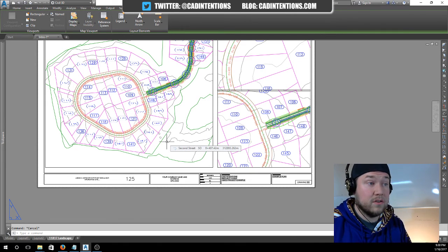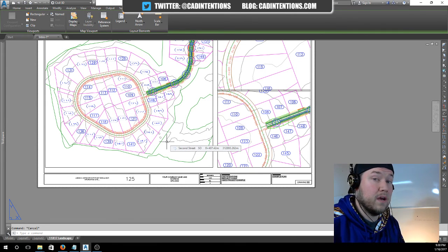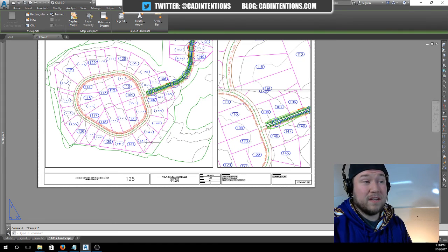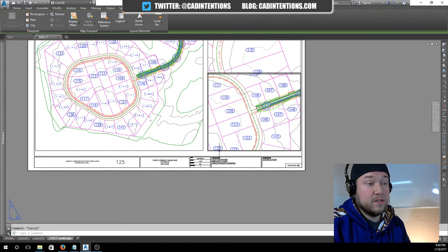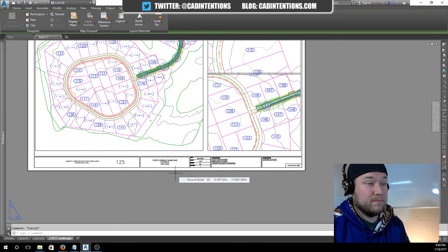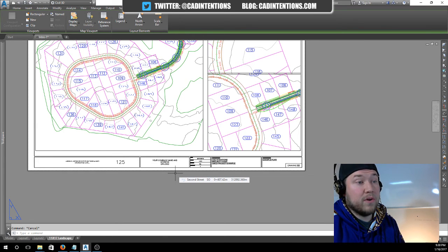Like dimensions, you're going to want in the model space, but part notes don't tend to move around with the parts or the sites. Legends don't need to move around, so you can put those into your paper space. Title block information. North arrows are debatable, because if you move or shift your north, you might want that in model space depending on what you're doing.